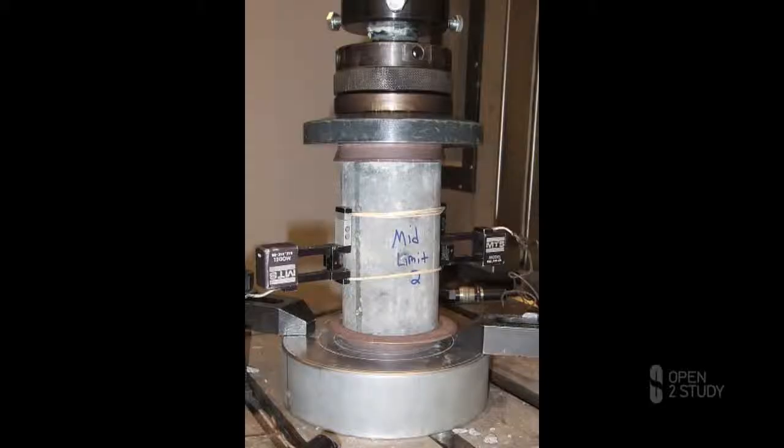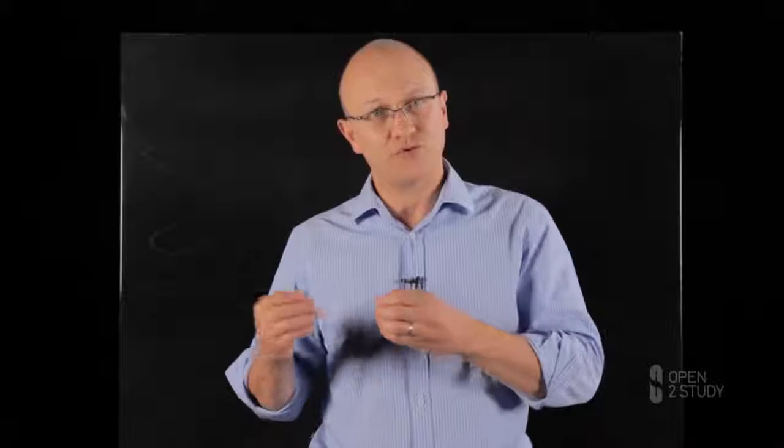In these tests, a rock specimen in a cylindrical shape is placed between two platens and is compressed at a certain loading rate with a measurement of force and displacement. These force and displacement are later converted to stress and strain using the relationships you've seen in topic 1. The unconfined compression test is used to determine the stress-strain relationship that we plotted in the previous topic to discuss deformability and strength of material.